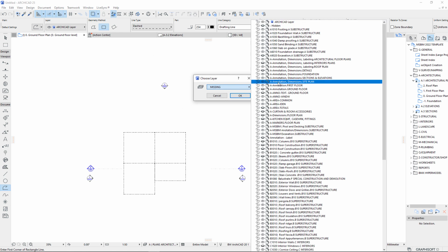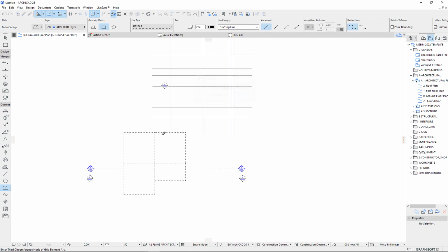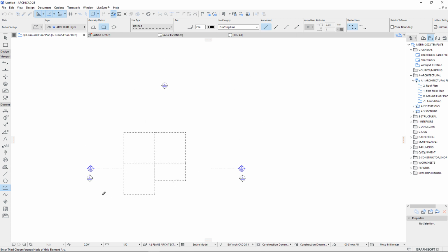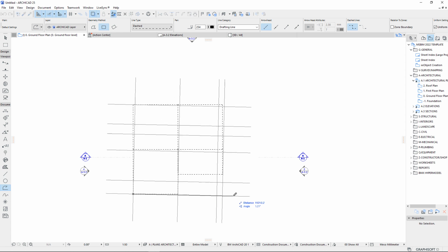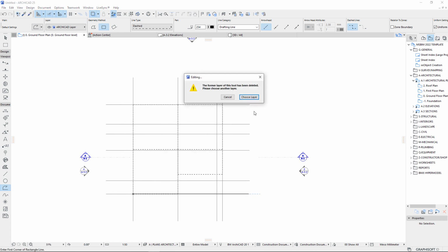I'll put them under a wall or structural wall grid layer, because they represent that. So I want something like exterior wall, then hit OK. Graphically it will be defined on your screen. So I'll click here to place. There you go, just like that.